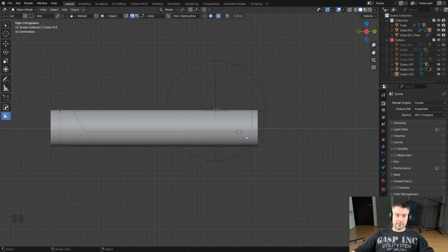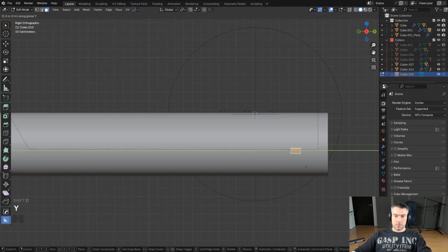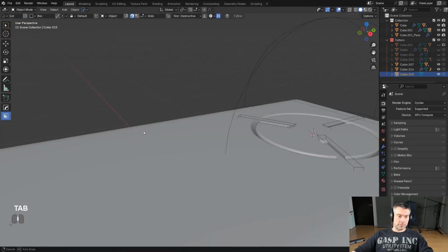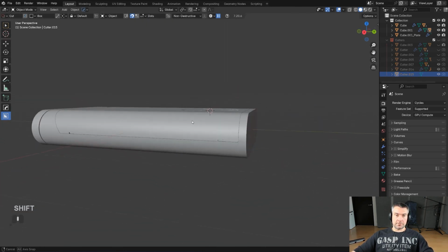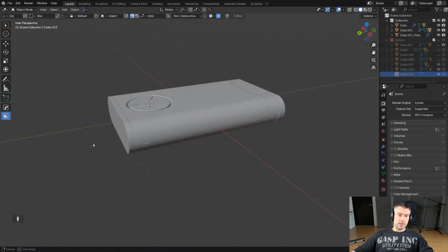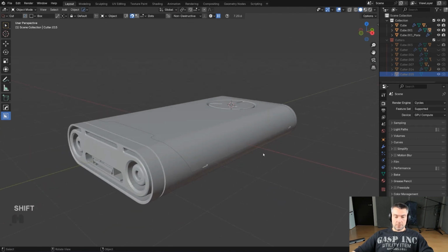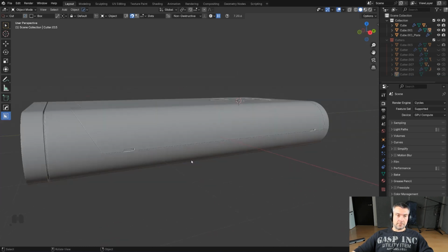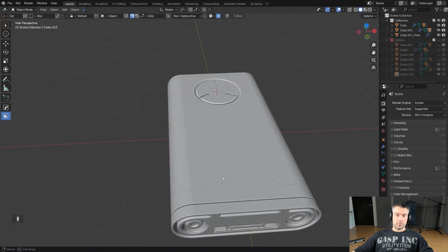If you want to duplicate the cutter, you can array this, or you can just simply move it. So select the cutter, go to edit mode, select everything, and then Shift D, Y, and you can move the cutter to wherever you want, and it's going to repeat it in edit mode, so you don't have to re-boolean this. You can either array this or do this. And you see this is kind of a tertiary detail area. It's going to add a little bit more interest to the mesh. We can go to Alt V with hard ups and add cavity because it disappeared, which is going to add a bit more highlights on the mesh. You can clearly see all these details popping up really beautifully, which is really cool.